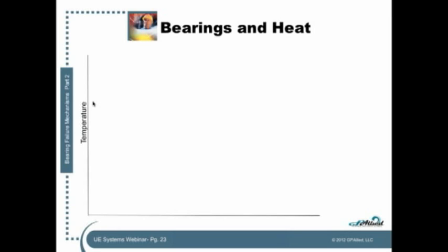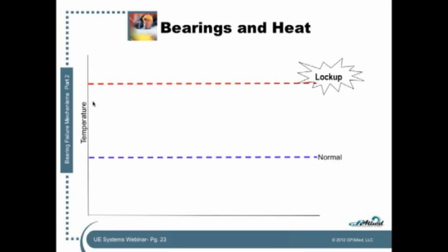We also need to talk about bearings and heat. There are lots of folks out there taking classes and teaching classes, and in their minds all bearings lock up, and that's just simply not the case. If we look at temperature and say that's representative of the normal bearing temperature, we do know that there is some upper temperature where, if the bearing reaches that temperature, it will lock up, it will seize, because everything swells in the bearing, the inner race, the outer race, the shaft, the balls, to the point where the internal clearances are gone and the bearing actually stops.